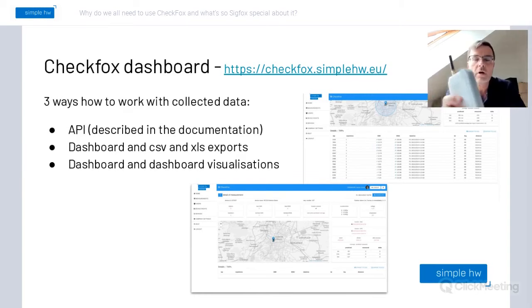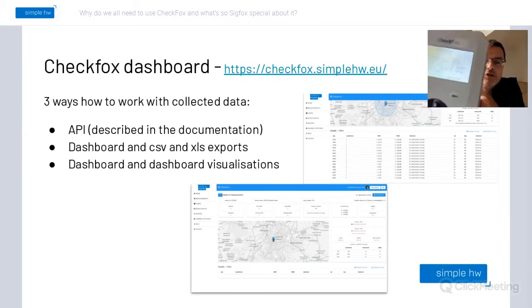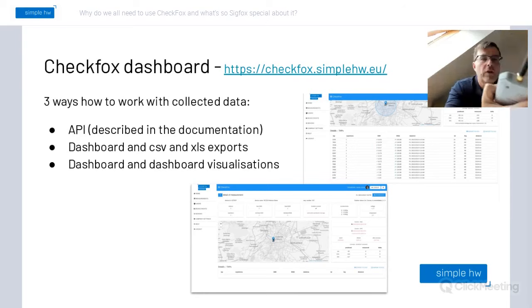Maybe I'll mention one more thing. The device uses a standby, so if you are not using it, it automatically gets into a standby regime. Default setting is 5 minutes, so it saves energy. And if you are not using it, the device switches off automatically after 6 hours. So even if the field worker forgets to switch it off, it switches off itself automatically. Of course, it doesn't switch off automatically if it's doing any measurement.